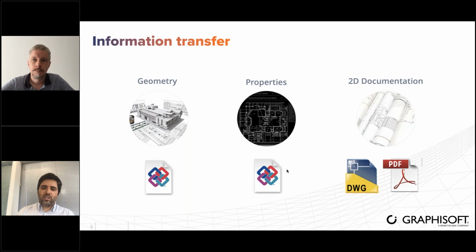So the whole industry is moving away from 2D documentation and all the manual process of representing one separate view from another and all this. So if you want to transfer 2D documentation, you just export the views that you have from your BIM model in DWG and in PDF, or the layouts, and then you can transfer that. So optimally, if you want to give a package with a model and the documentation, you should give them IFC or multiple IFCs and DWG and PDF files, or multiple DWGs and multiple PDF files.